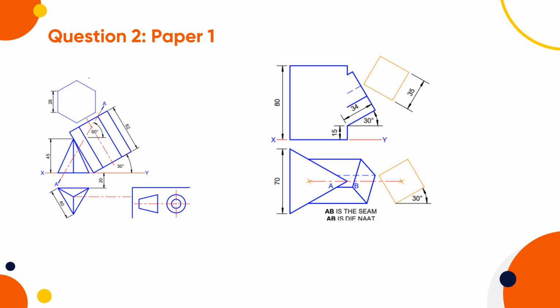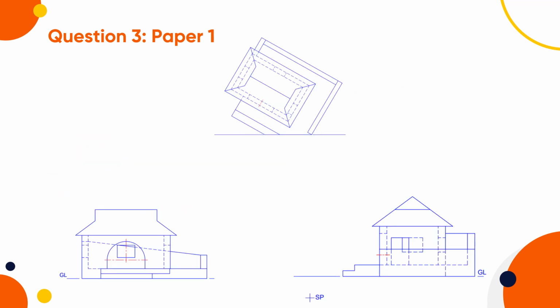Question 3 focuses on our 2-point perspective drawings, especially the new part to the 2-point perspective drawings that we've done this year, and that is the 2-point perspective circle and the construction of it, including also using our ground lines, height lines, or our picture planes to make sure that we have the page correctly set up onto our drawing boards, and that these lines are parallel to our T-square or our movable ruler.